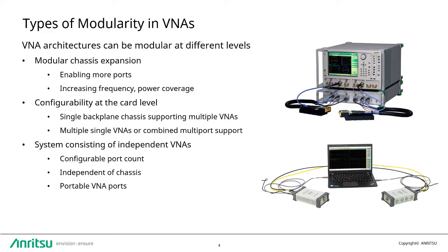Modular architectures can be classified into three major classes. Modular by chassis, where test sets and other instrument building blocks are added to a base VNA to add functionality like additional ports or increased frequency or output power. This type of modular VNA must have expansion support built into the base VNA architecture, which differentiates it from the